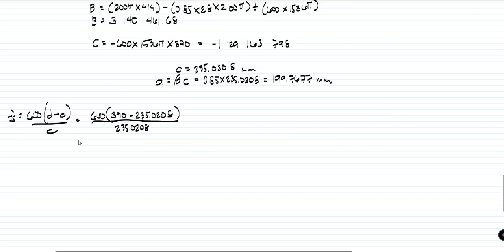So fs now will just be equivalent to a value of 395.6566. This is in megapascals, and this is lesser than 404 or 414, so lesser than fy. Therefore, the assumption is correct that it still does not yield for the tension.